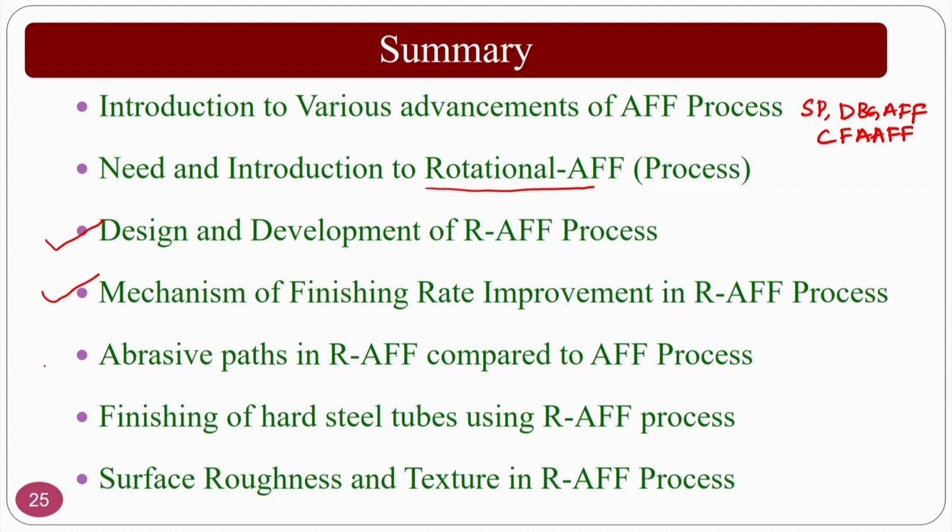And abrasive paths, we have seen the abrasive paths' angular motion is reduced, okay, and this can increase the contact path or the finishing path, so that the finishing rate will be improved. And not only the flat surfaces, we can also finish the hard steel tubes in this particular process, and we have also seen the surface roughness and texture that is generated. And what we have seen is that it is not only for the application of the surface finishing process, you can also generate the surface textures like crosshatch patterns that are normally used in IC engines.